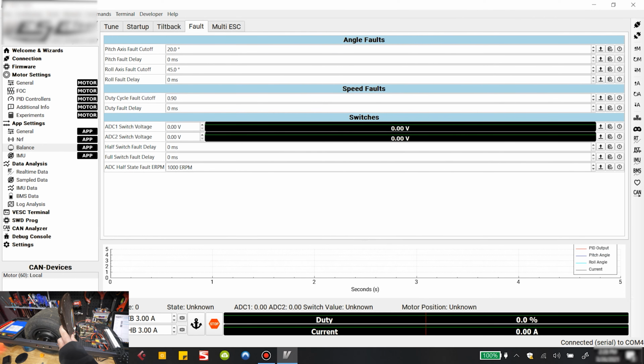Without pressure on it, the resistance is at its general maximum, so there is not a lot of voltage coming through to the controller. When you put pressure on the pad, the resistance goes down, and so the voltage reading on the controller goes up. How does that work? You stand on it, you add pressure, and it reads it.